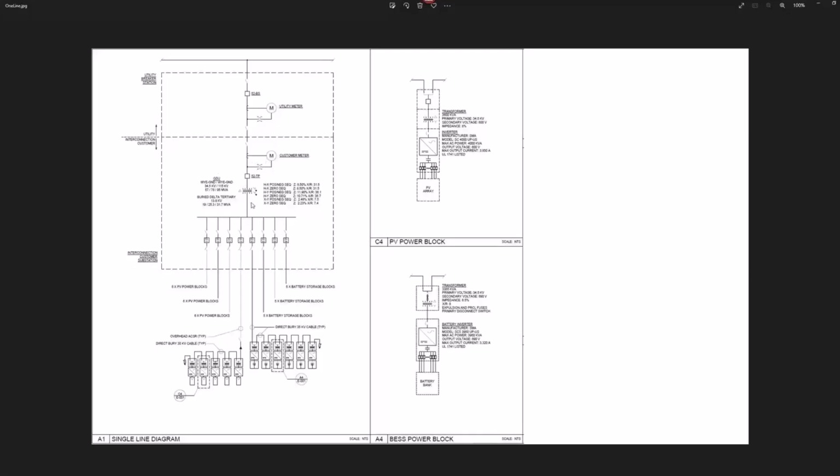You have the main power transformer. In NERC's world, it's called a substation transformer, right? In many utilities, people call them main power transformer. And then you have your collector system, collector cable equivalent. I think we discussed the collector cable impedance equivalent in some webinars we had like 2 or 3 years ago. If you have interest, please feel free to browse back to see how to equivalize the collector system. But here, since we are doing harmonics in detail, we have to model every collector cable explicitly instead of having an equivalent system to represent, right?